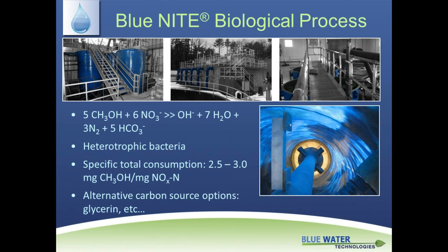We can get some slight scrubbing of seleniums and sulfates as well with a biological treatment system. But mostly our focus is on the nitrate uptake and removal because it's a very high efficiency process and requires anywhere from 10 to 20 minutes for most of our applications, which is residence time that we can achieve.